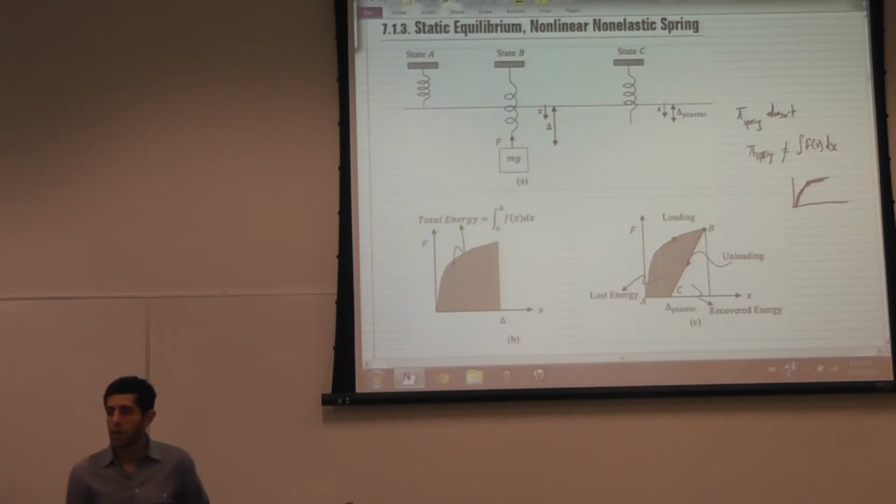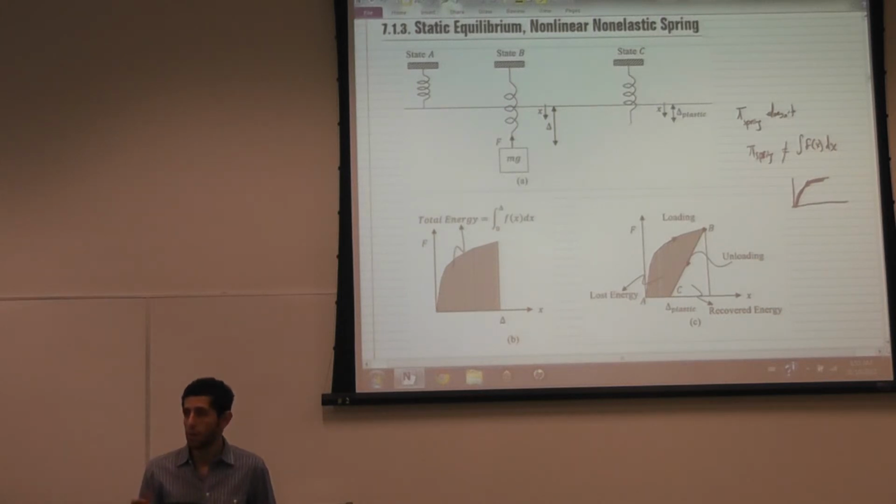If I keep loading and unloading, without actually reaching the ultimate tensile or maximum stress that this material takes, and keep damaging the material, sooner or later it will just snap. Unless I'm loading and unloading in an elastic manner, but usually as long as there's some dissipation of energy inside the object, I'm causing some damage that will eventually lead to this spring breaking.